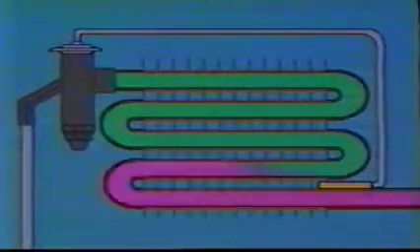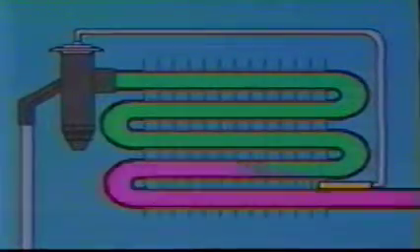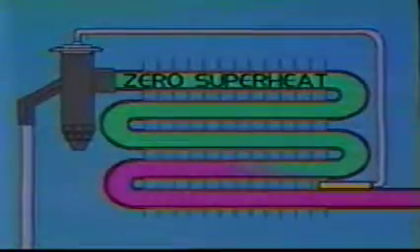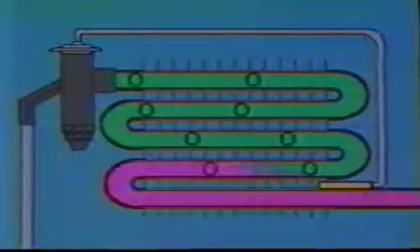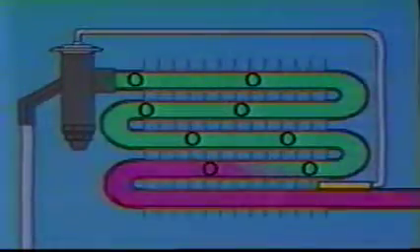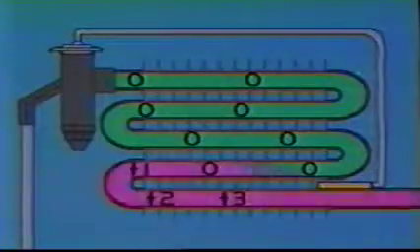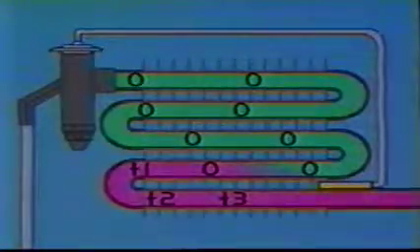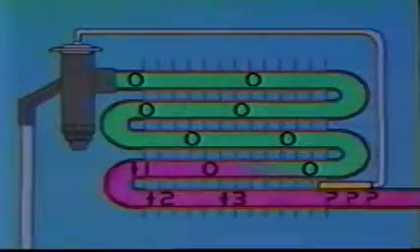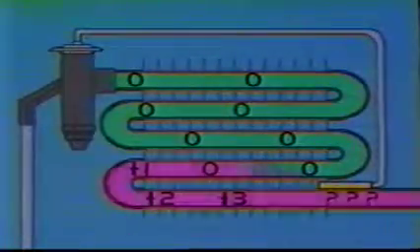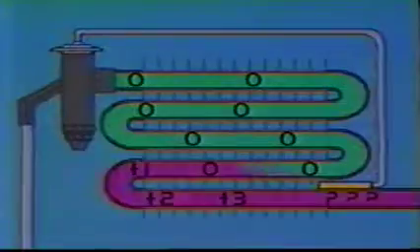While there is no actual clear interface between liquid and vapor in an evaporator, at the inlet to the evaporator, there is mostly liquid starting to evaporate. At this point, the superheat is essentially zero. The superheat level will remain near zero until liquid is no longer present. The superheat will then increase at each point in the evaporator tubing as we get closer to the suction line. It is the superheat at the outlet that we are most interested in controlling with the TEV.